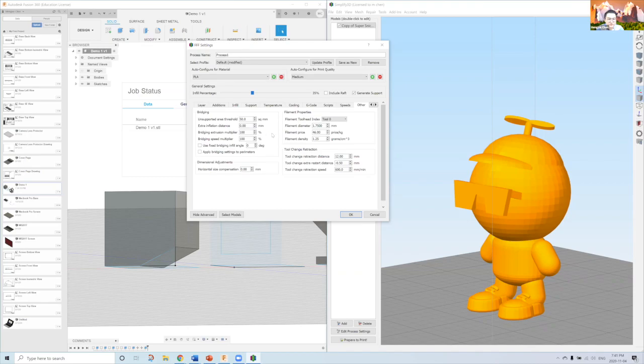Or you can also customize the infill for the bridge. When you do a bridge, you want to have solid infill at the bottom because it's considered a surface. But you can also customize the angle for the infill of the bridge. If you only print horizontal lines between 2 points, it's going to come out better in terms of quality than if you print the outline horizontally and the infill in a different direction.